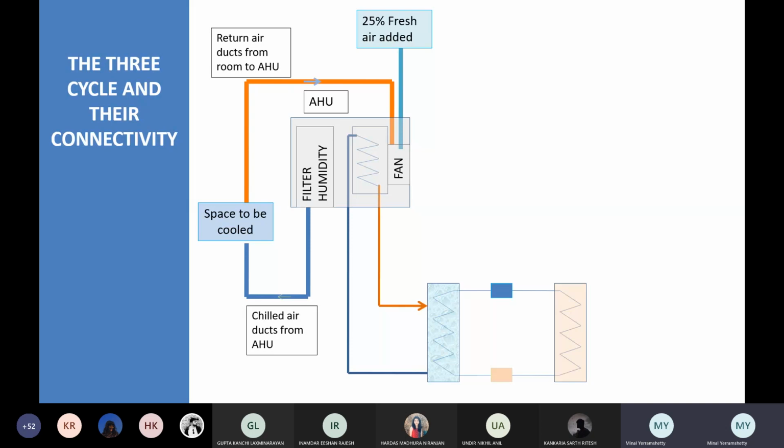Now this liquid refrigerant, when it is coming here, it takes the heat from the water. This blue thing is the water. Okay. In turn, what does the water do? It gives away its heat and becomes chilled. Okay, and that chilled water is brought here, and then it is circulated and comes back and again goes up and comes back. So this cycle keeps running in its own whimsical manner. The fan is running its own cycle, and this is running its own cycle.